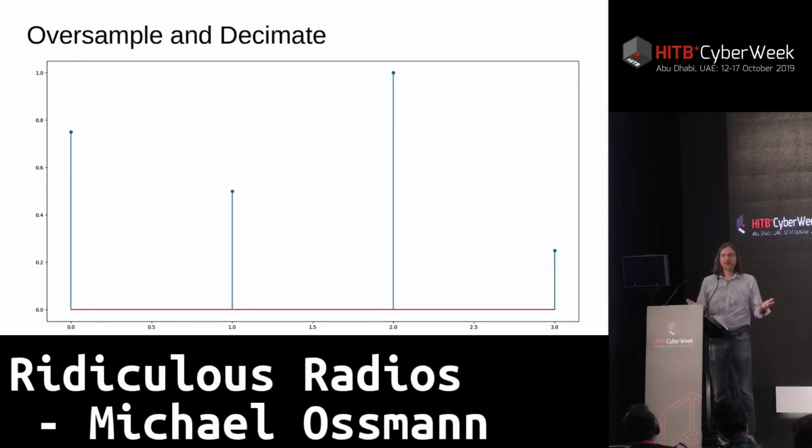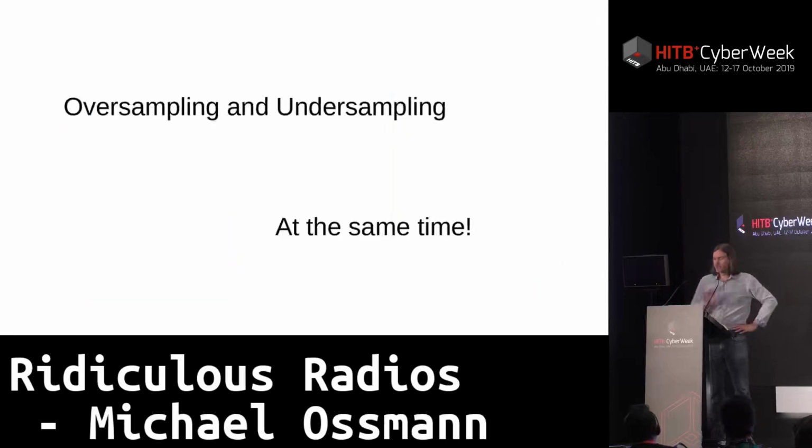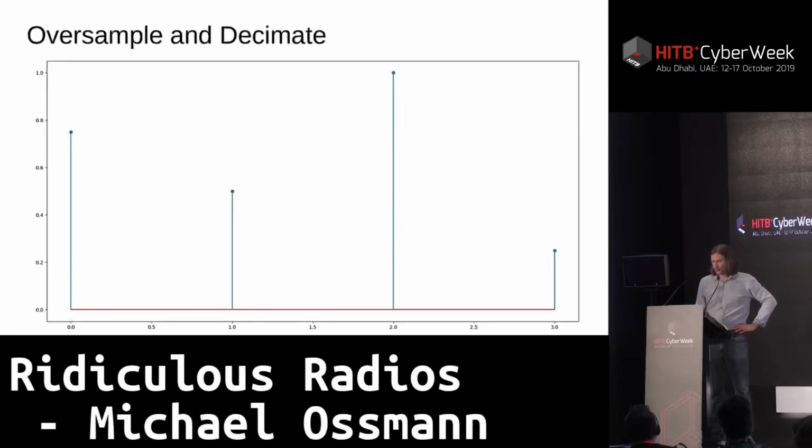You need 9 bits to represent all the possible results of that addition of 2 8-bit numbers. And the same thing we're seeing here. When we add 2 samples together, we increase our dynamic range, or we increase the number of bits per sample. We can continue this as much as we want, up to a limit of how slow we're able to make our sample rate. Because every time we divide our sample rate in half, we gain 1 bit of dynamic range.